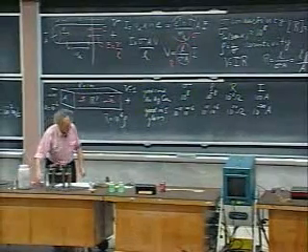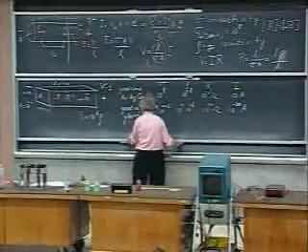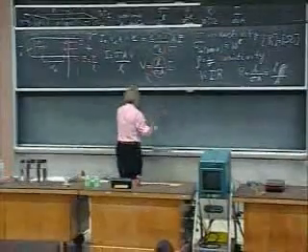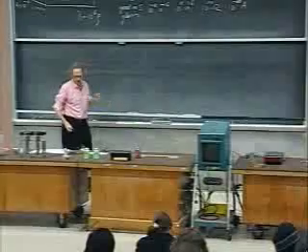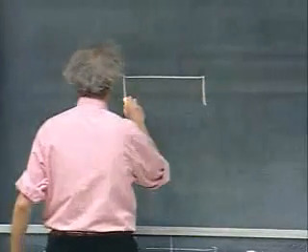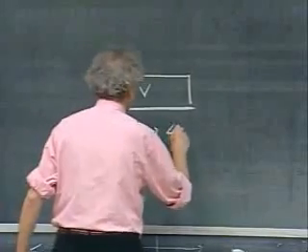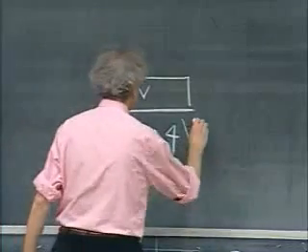I first want to demonstrate to you that Ohm's law sometimes holds. And I do a demonstration whereby I have a voltage supply, put a V in here, and we change the voltage in a matter of a few seconds from 0 to 4 volts.